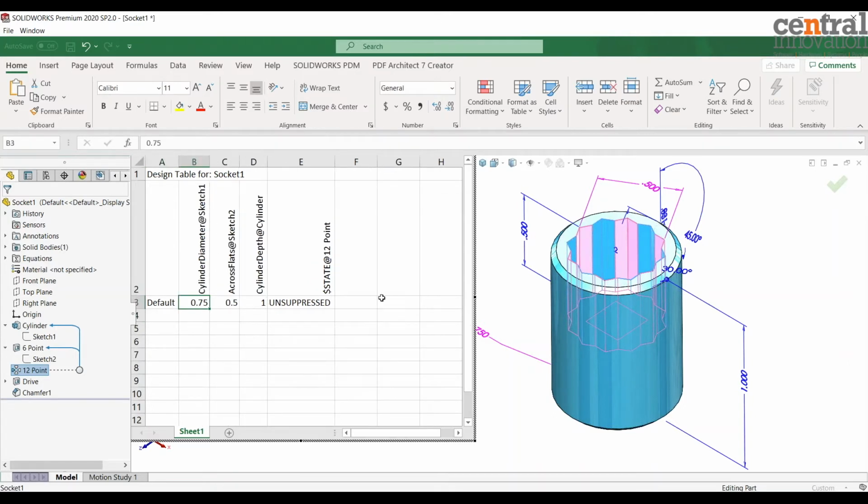Now I will add the other thing that I'm going to address here. As you could see, the diameter of the cylinder needs to be changed according to the across flat dimension change, because it's indicating the wall thickness that I showed you. So here, instead of having one value, I'm going to change it to an equation. Again, as you can see, the functionality of Microsoft Excel is really helpful for us to control our dimensions and features to create different configurations.